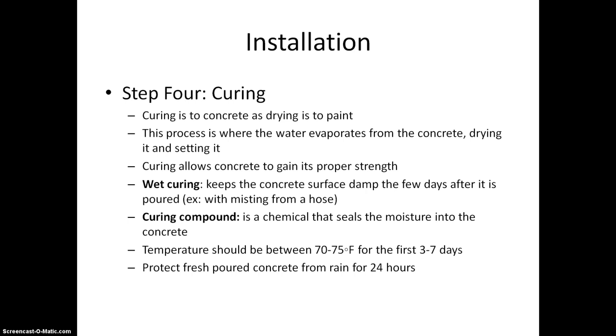Wet curing keeps the concrete surface damp for a few days after it's poured. An example, you can use misting from a hose, or you can use a curing compound, which is a chemical that seals the moisture into the concrete.